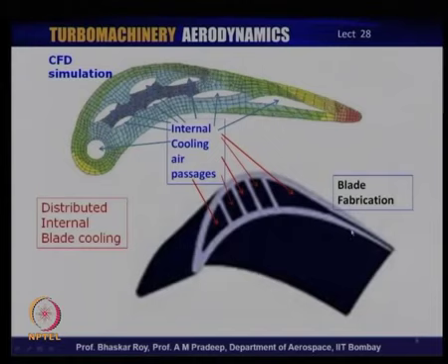So, the modern method has facilitated a process by which the cooling air finally may exit through the trailing edge, cooling the trailing edge itself. So, those are the various technologies that have to be brought into the turbine cooling business.